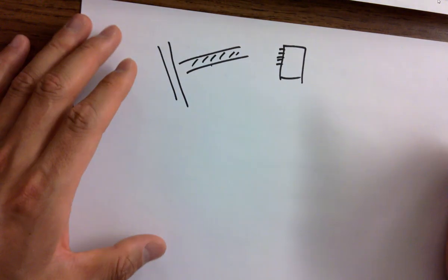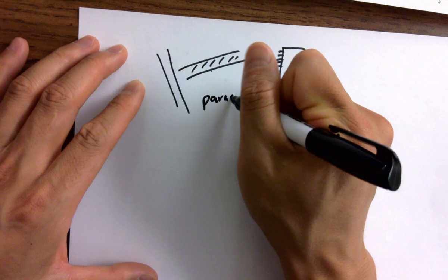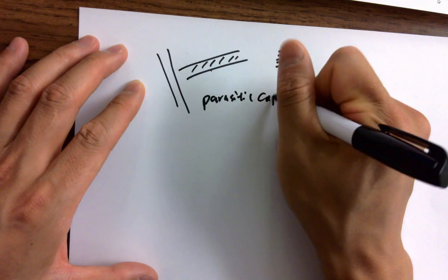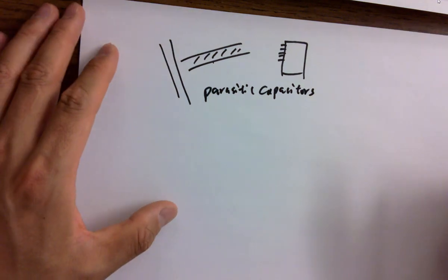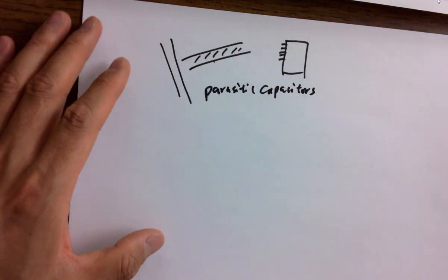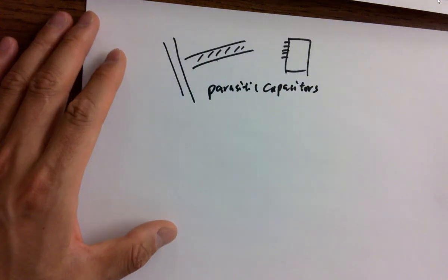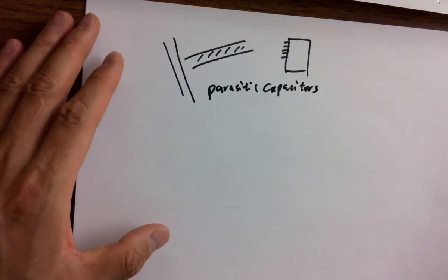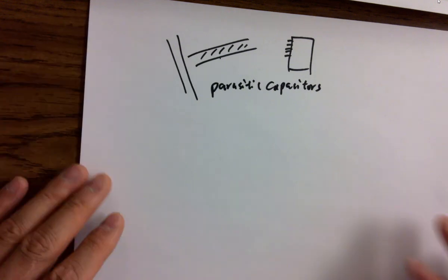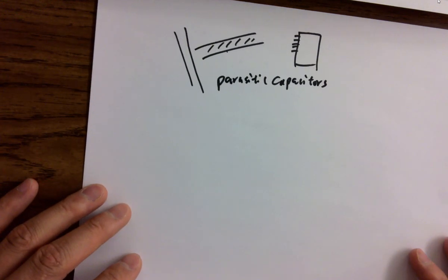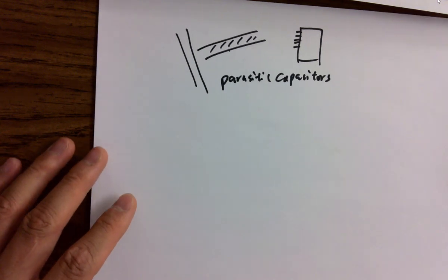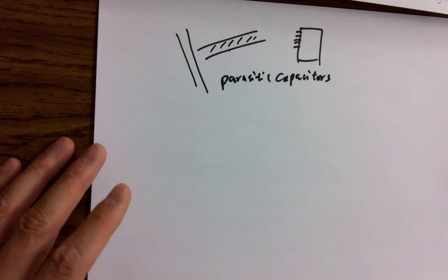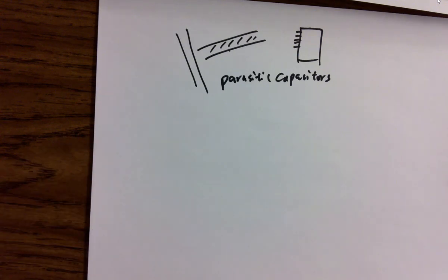So this is forming capacitors. They're called parasitic capacitors, like parasites, but just everywhere. Also the wires are metal, but they're not ideal. They're not superconductors. They have resistance. So when you are injecting currents or driving a certain circuit, you got R's and C's. They are either in series or in parallel, doesn't matter. But eventually, you can conclude everything to a model, which is a fundamental RC circuit.